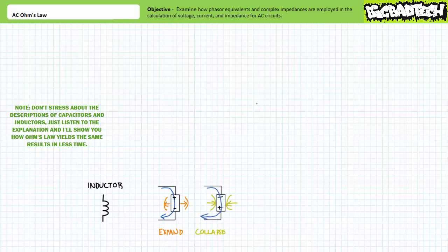Experiencing a decrease in current, the collapsing magnetic field continues to push current out of the bottom terminal by generating a voltage differential across the inductor, positive to negative, bottom to top. In this sense, the inductor is acting just like an active element, supplying energy. The other half of a sinusoidal cycle would be a repeat of the previous process, only polarity is swapped.